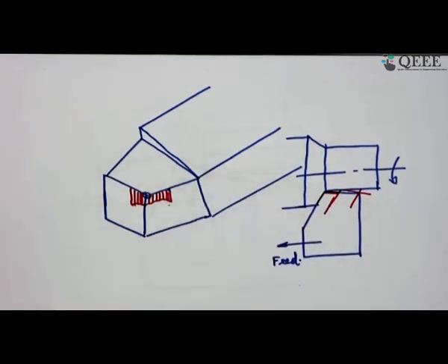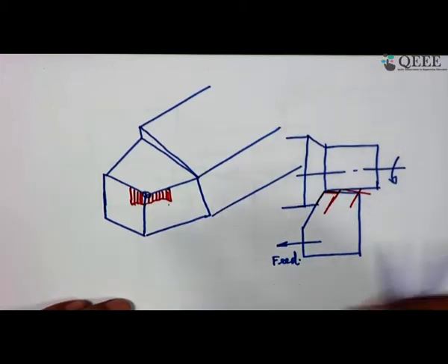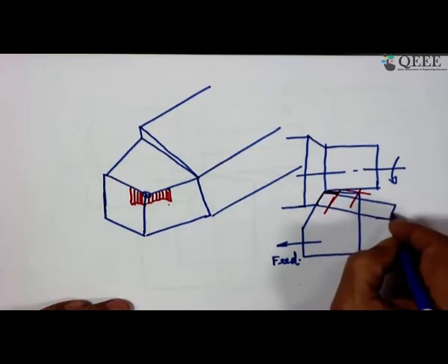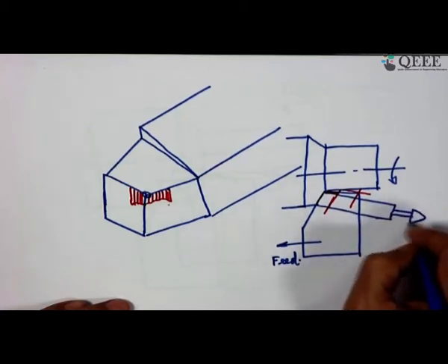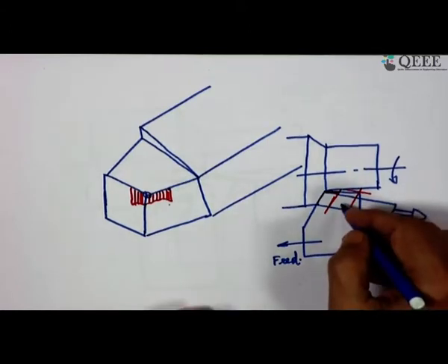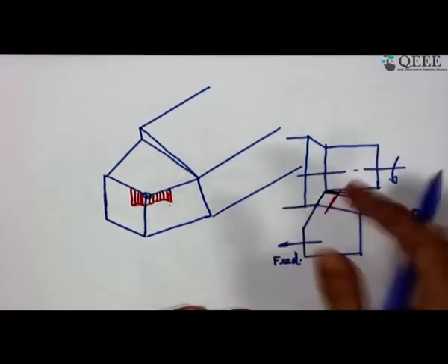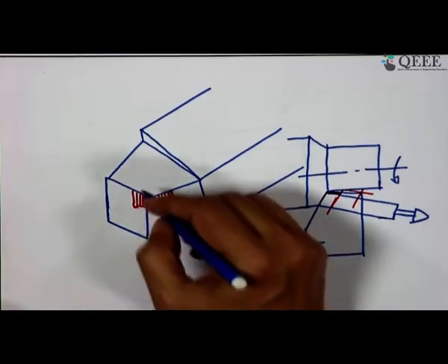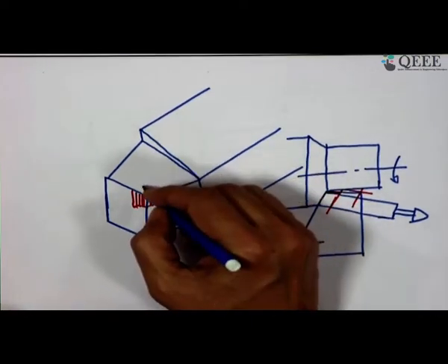So, this is the wear on the cutting tool, and in addition to that you can imagine the chip is flowing like this. This is the direction of chip flow, and as a result you also have rubbing contact between the chip and the tool surface, and an impression is left in the form of a cavity, like this.